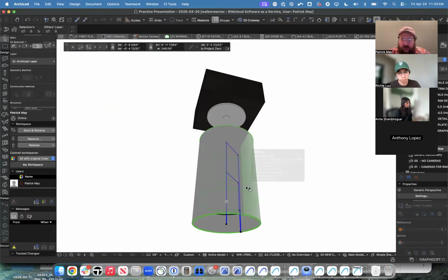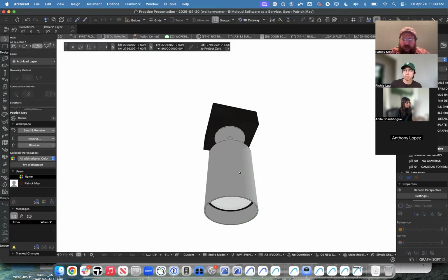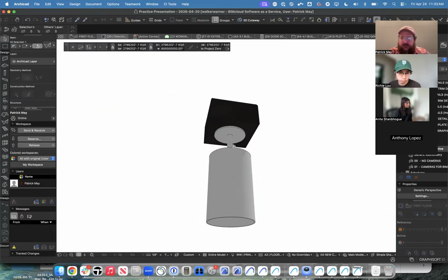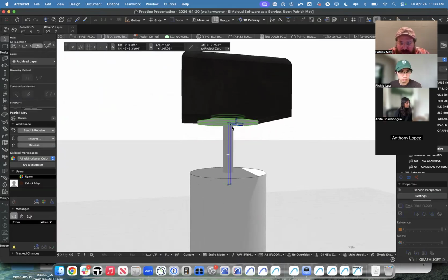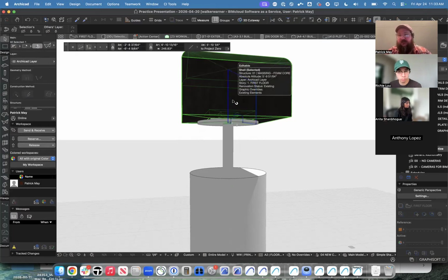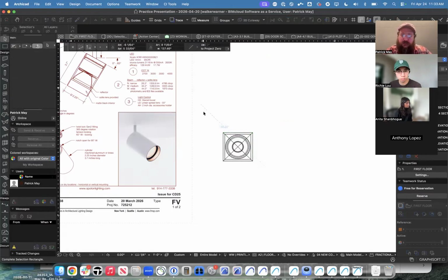Right, so I have a few different shells on here. I have 3 shells for the main light housing. I have 1 shell for the ceiling fixture that includes that sort of reveal. So really all of this stuff needs to be saved from this point because that's going to be flush with the ceiling. And then the junction box sits here. And all of these are just revolved shells. So let's grab this stuff and move it into place.